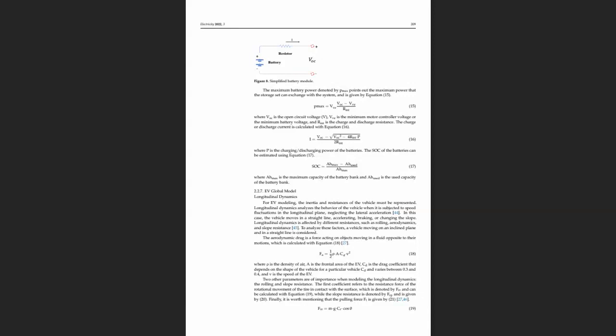You will convert it to watt hour. If you use the minus equation, I say again, battery capacity minus motor consumption, it will give you the battery level, state of charge.